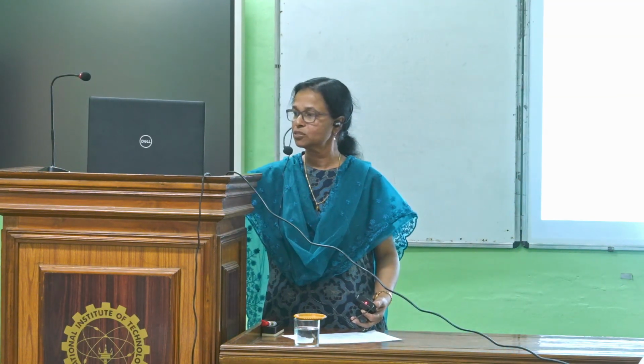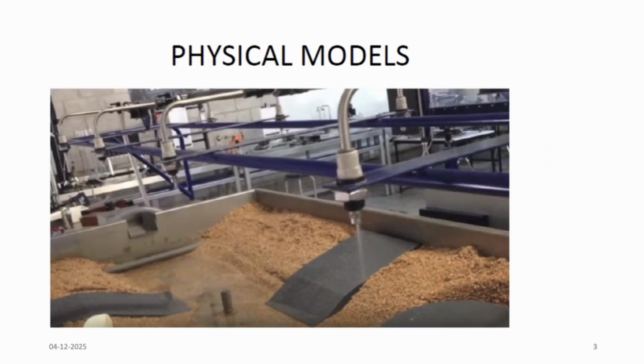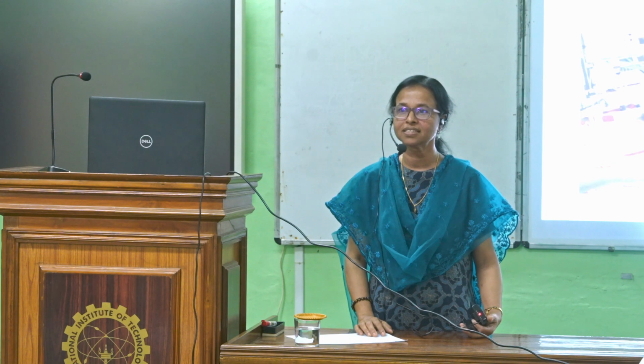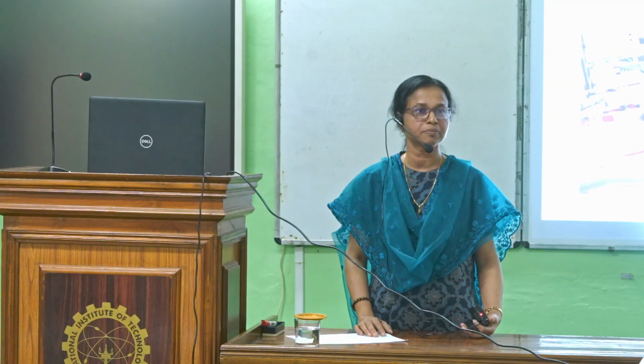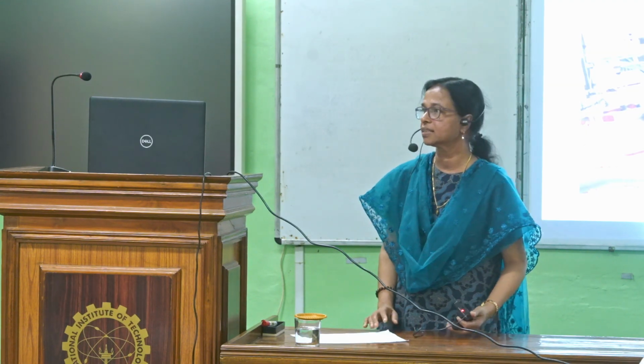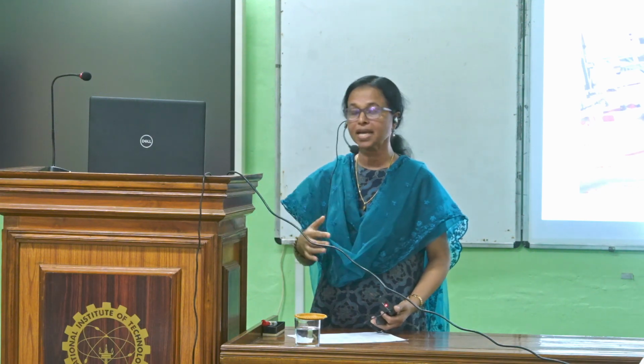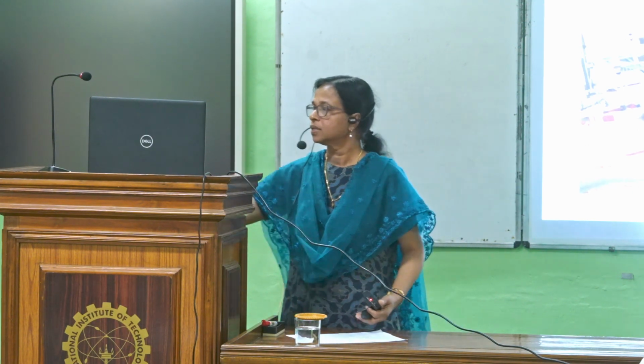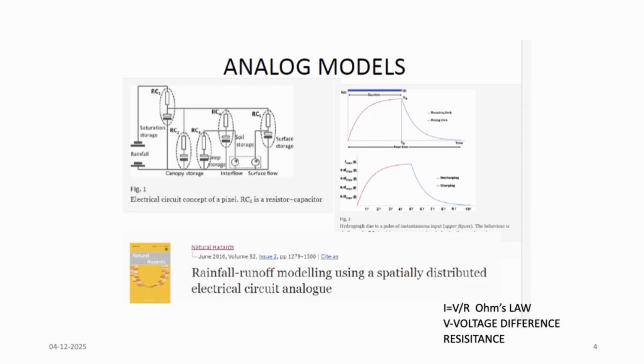In a physical model you have to check the similitude. You might have studied in your fluid mechanics the similarity laws, geometric similarity and dynamic similarity, which have to be obeyed when you construct a physical model. A sandbox model for groundwater flow is an example of a physical model.